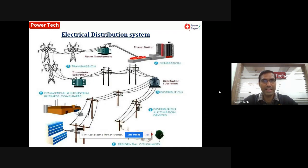This is a basic diagram for an electrical distribution system, where you can see the energy is being generated at the power station at 11 kV. Then it is stepped up using a power transformer to a higher voltage. The advantage of transmitting the power at higher voltage is that the loss would be less, because current I would be less, so I square R losses are less, and at the same time, when I is less, the conductor size would also be less. Therefore, that's the reason why we transfer the power at very high voltages when it has to be transferred over long distances.